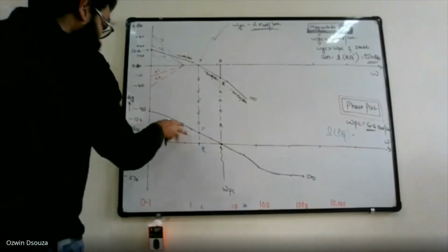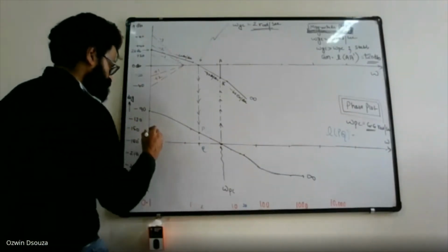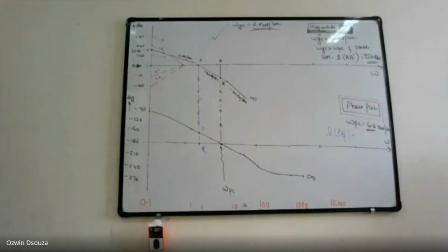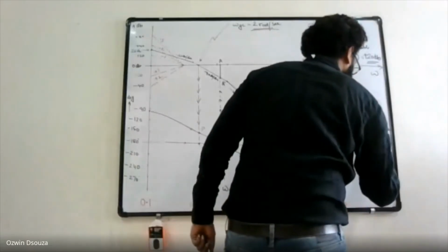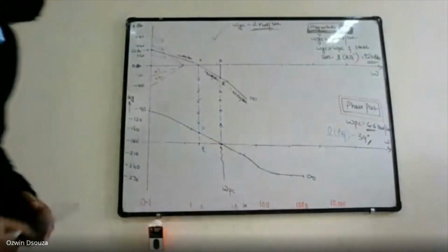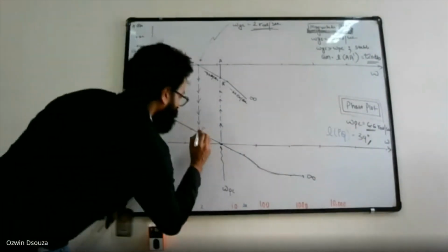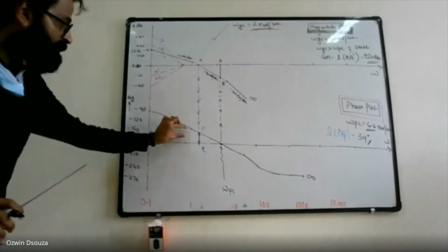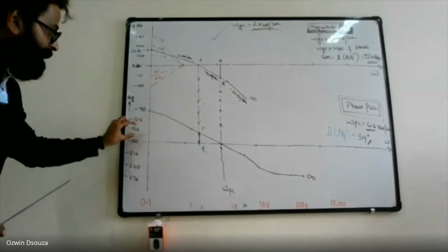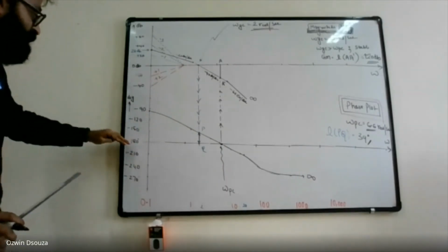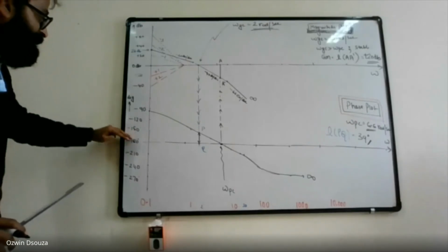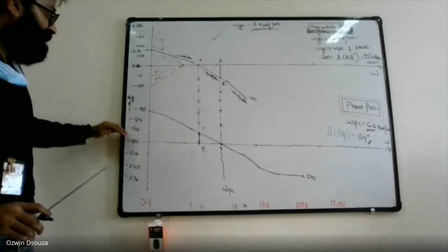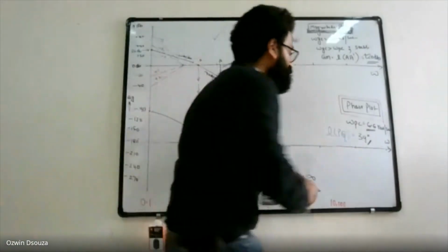When you multiply with scale, you will get the phase margin. It looks slightly above 30 degrees, right? Because if you see till here it is 30, slightly above 30 degrees, 39 degrees it is coming. So phase margin is 39 degrees. Where is the phase margin getting located? It is located on the increasing angle side, right? See minus 180, minus 150, minus 120. So angles are increasing over here.